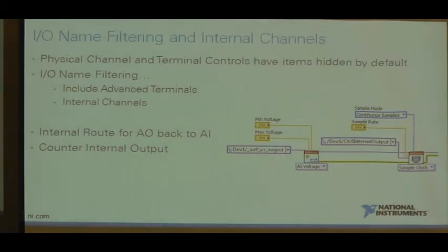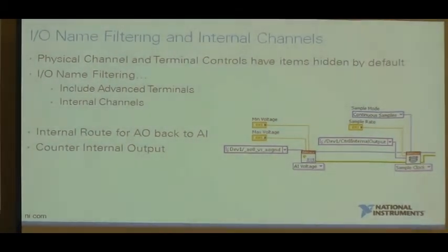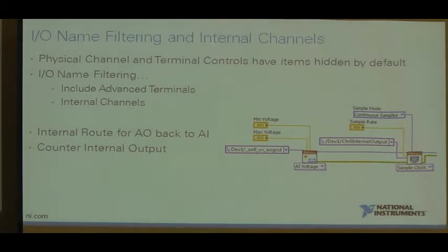So next we have I/O name filtering and using internal channels on your DAQ device. By default, when you click on a control for a physical channel or a terminal in DAQmx, we're only showing you part of the picture. We're only showing you the most common terminals and channels that are available to standard users. There are many more items available for an advanced user if you know how to get to them.